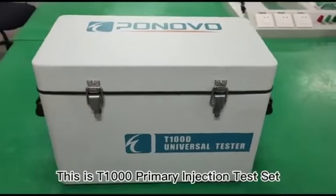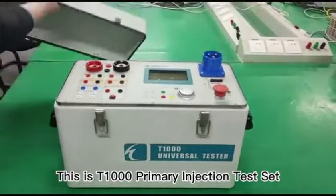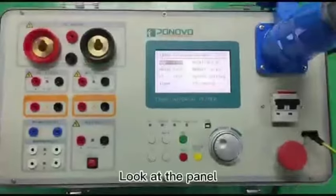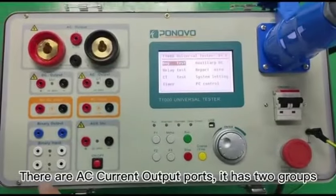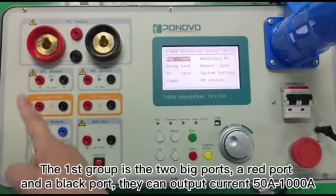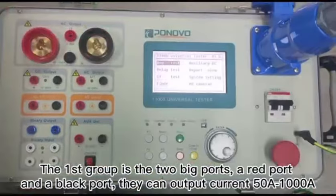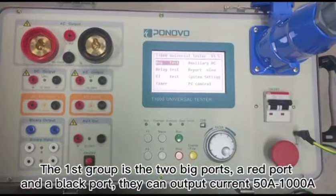This is T1000 primary injection test set. Look at the panel. There are AC current output ports. It has two groups. The first group is the two big ports, a red port and a black port. They can output current from 50 amperes to 1000 amperes.